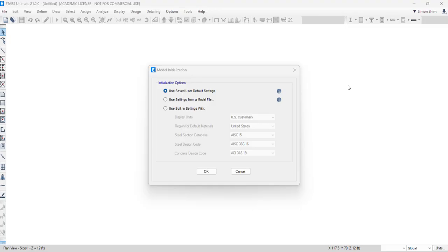So we're gonna just expand our learning of ETABS, 30 by 40 feet. We studied last week. I hope you guys get kind of familiar with beginning ETABS: how to draw, start out setting the unit and grid, the floor elevation, the section property and material property, and draw the column, girder, beams, and slab, and assigning loading and analysis. Those are all similar. In most projects, we are doing the same thing over again.